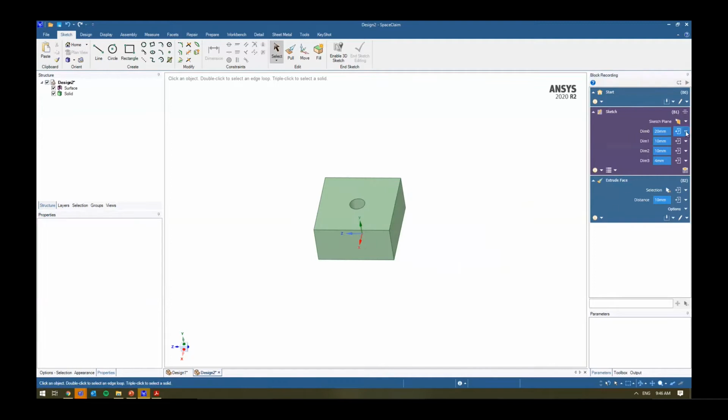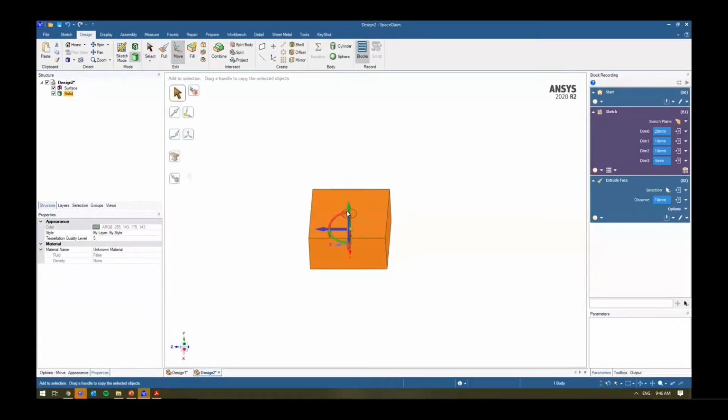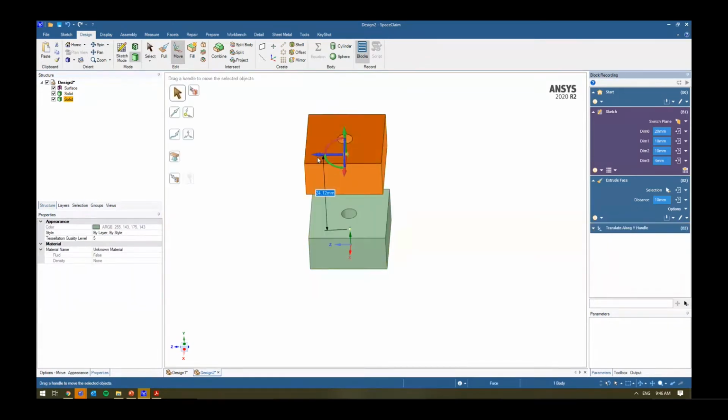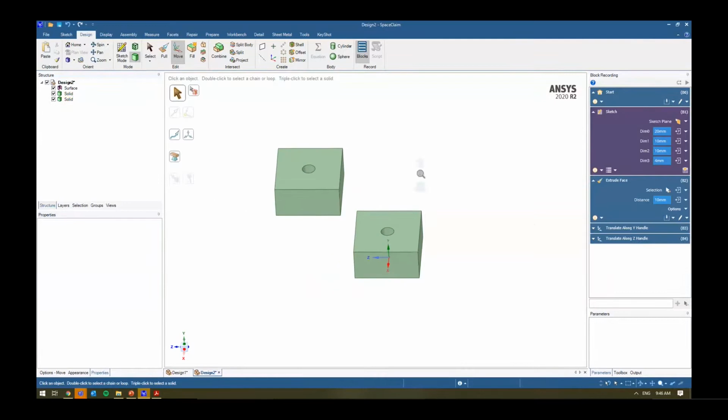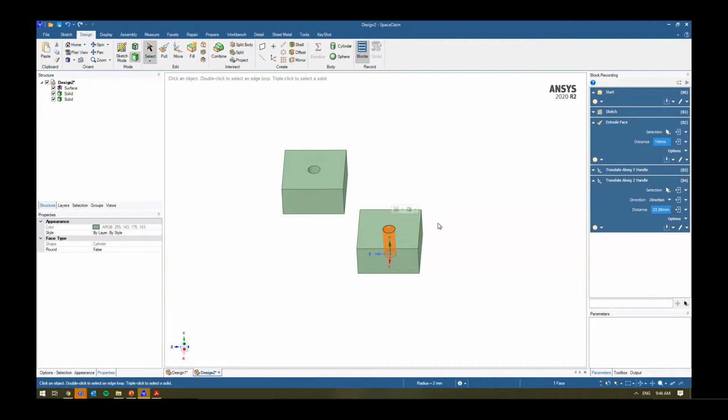regenerate everything for me. I can make things like parameters in this block sketching mode, and we can import it into Workbench as well. So if we need to do some parametric analysis where we're creating geometry, we can definitely do that. Right. Again, similar to before, so we can take something, use my design tool. So if I use my move tool, let's just say we move this up and around, everything's being recorded for me over here.